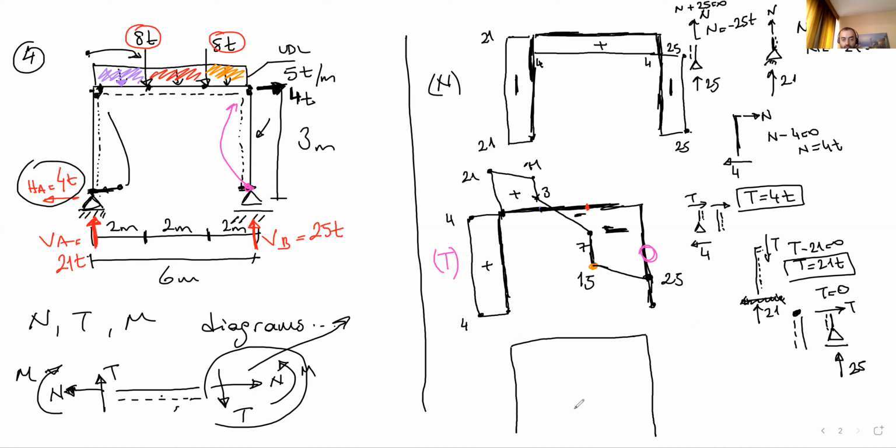Here we go. So at this point, at this support point, we have a pin support, so moment is 0. This is my start point, by the way. Remember, the viewpoint is here inside. So inside is the positive side for the moment, but no worries.